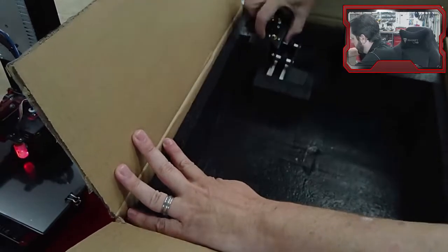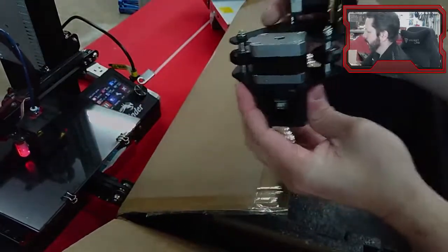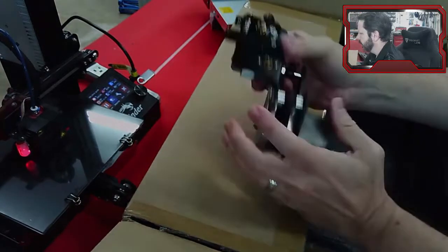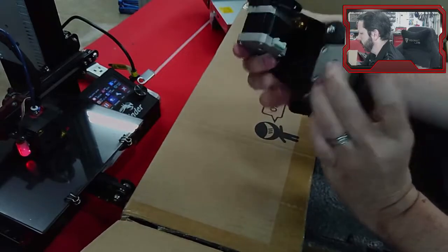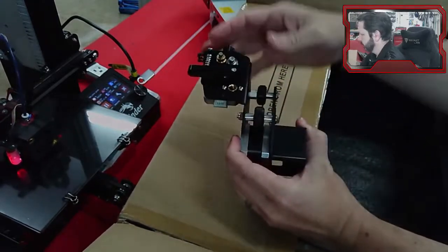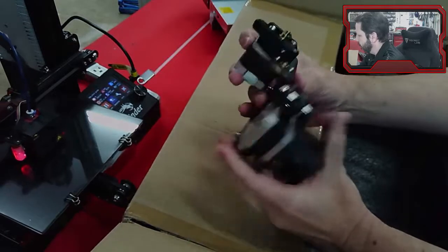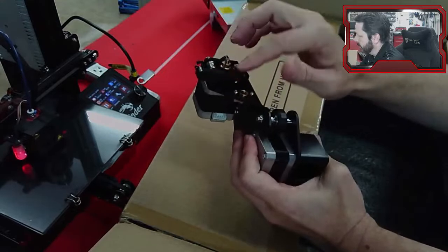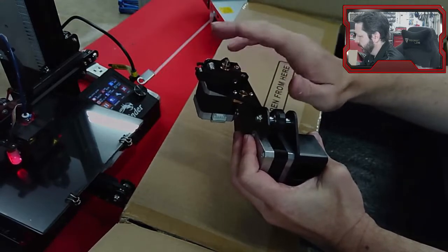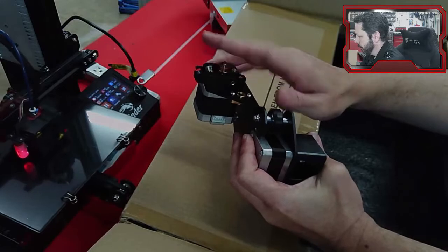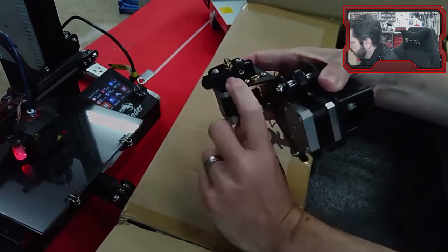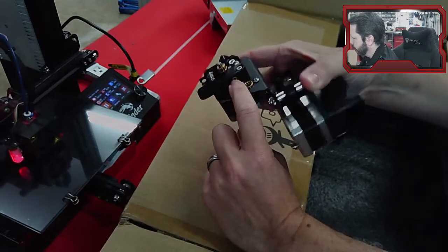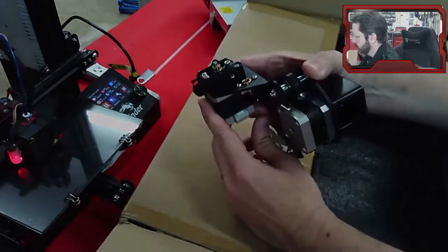So here's another big piece. This has got the X and Z axis on it together. Well, no, this is just going to be the X axis, back and forth, and the extruder. So one thing you want to look for on these extruders is this part. This is one of the pieces that I'm going to replace later on, but it's all plastic on the Ender 3, and if yours doesn't have the little metal insert here, over time the filament goes in this hole and gets pushed out here to your hot end.